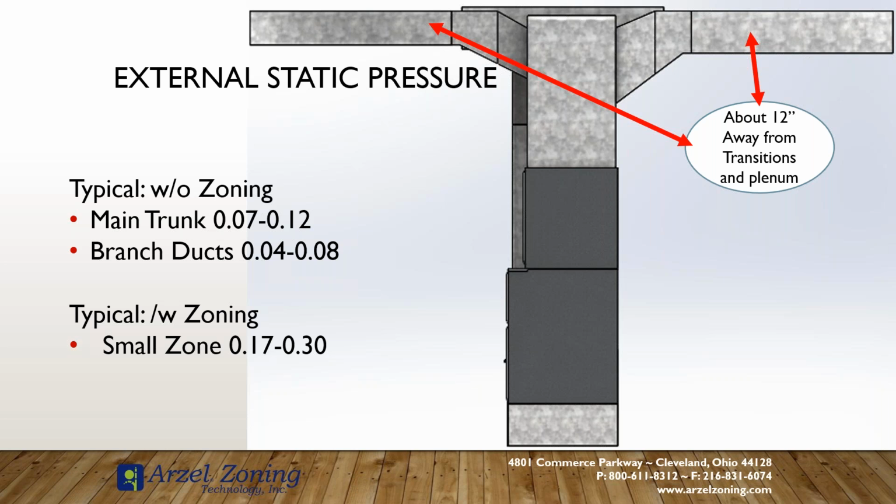Now in reality, we're going to see that it's significantly higher than that when we start testing equipment, because we're finding that furnaces are oversized for the ductwork or the ductwork's undersized for the furnace. Now our equipment needs to be designed to handle the actual load that the house needs. And then once we have our equipment design, we need to make sure our ductwork is designed to match that equipment. If the ductwork is pre-existing, this is where it's important to try and recognize what improvements we can make to have the best performance impact on that equipment to give them better operation.